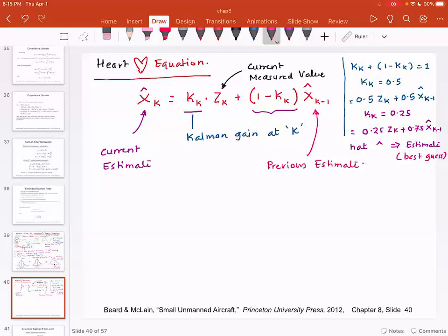So what we are doing here, if you think about the example, is that you have a light source, and this light source is flickering or it is changing. And you have some sort of measurement device, maybe an optical diode, or some sort of illumination sensor, some sort of photoresistor that is giving you a measurement. So just think about it like you have a photoresistor and that is giving you the intensity of light. Every time I'm going to get the measurement from this photosensor, I'm going to call this zk. And I'm going to have in storage the previous estimate that I calculated.